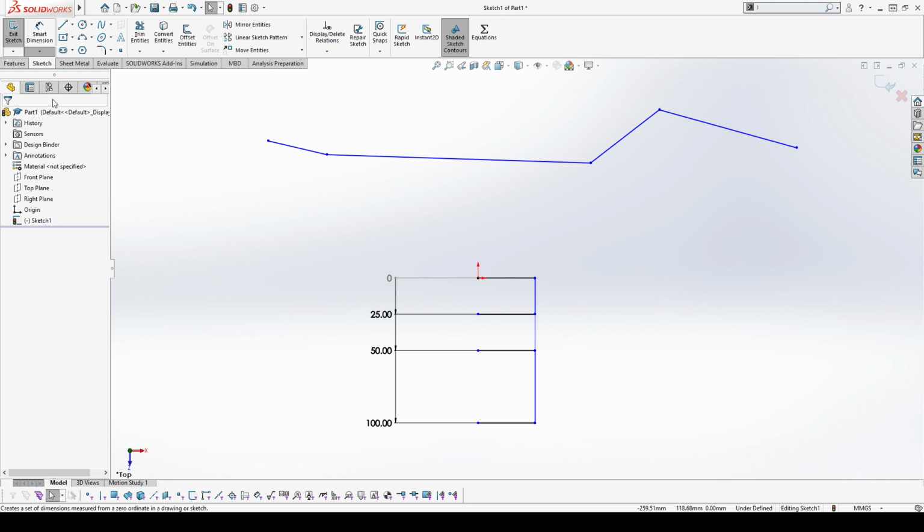with that ordinate dimension, we can kind of do the same thing and specify that it's horizontal or specify that it's vertical. And then there's a path length dimension, which we won't talk about because that's very rarely used. I personally haven't used it myself in my last 5 years of using SolidWorks. But, kind of as we were talking about before with the arc lengths, that's where you'd use a path length. It's that equivalent line that we're drawing out, and that's how long it's going to be. So that's all of our dimensions there.